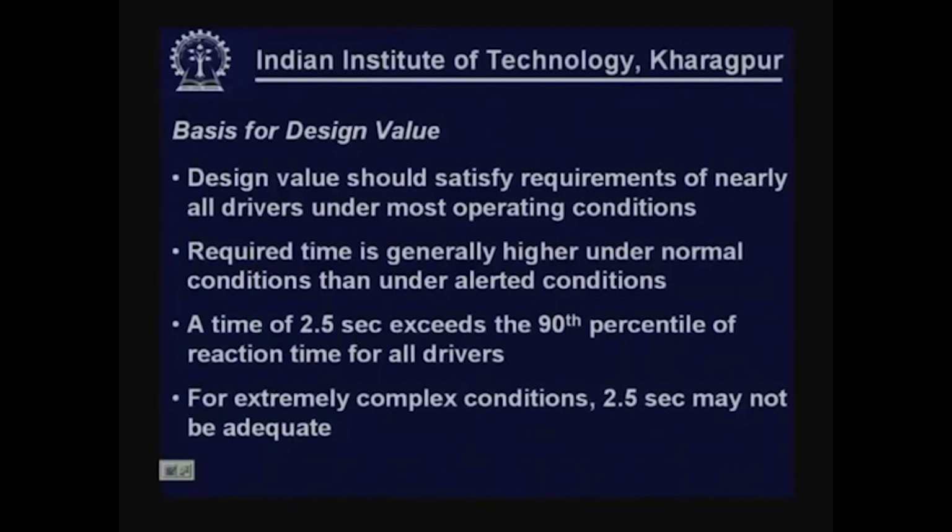Basis for design value: design value should satisfy requirements of nearly all drivers under most operating conditions. Nearly all drivers may not be 100%, and most operating conditions, not all operating conditions.